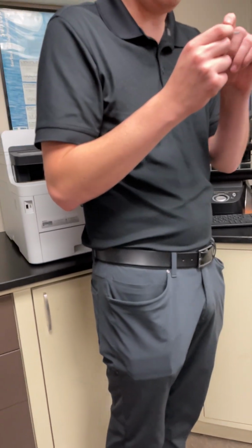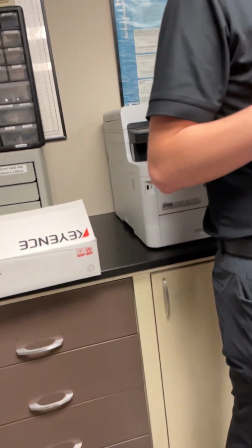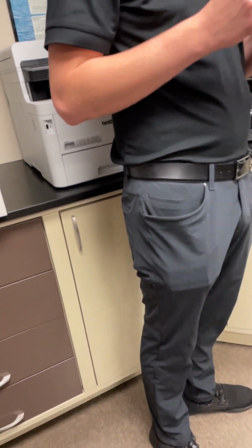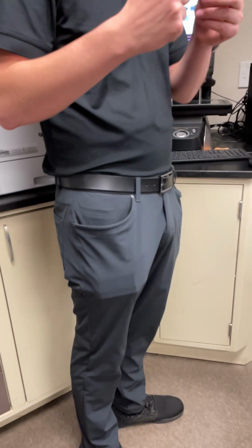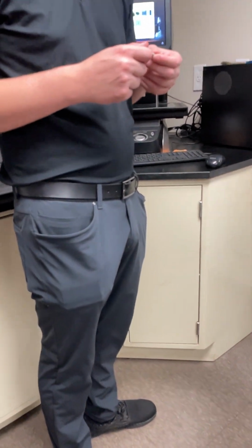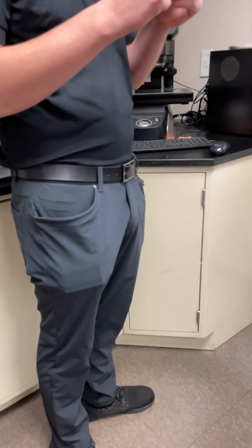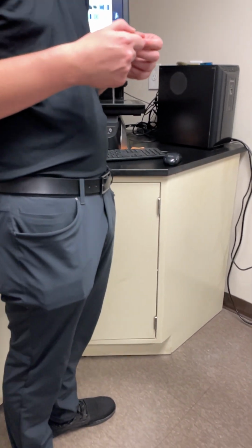But is it only on one specific area, or could it be the whole diameter as a whole? The whole diameter. Then that's what I would do. Otherwise, if it was only in one specific area of this diameter, the only way I could do that is if I had the rotary. Then I would make sure of my reference angle, and from there do a full 360 degree scan check on it, and it would let me know.